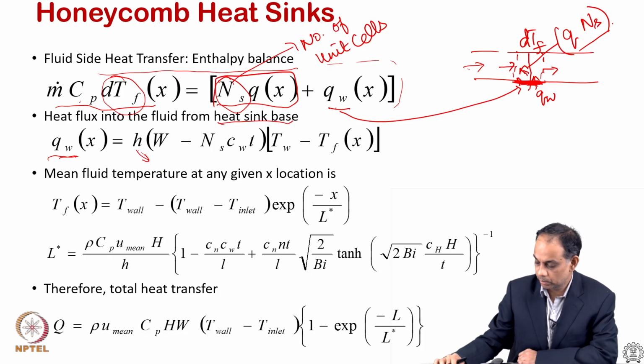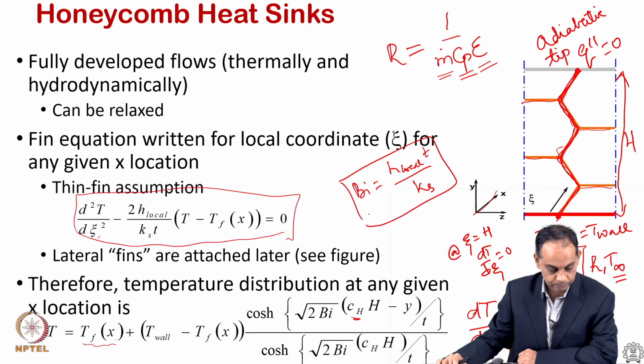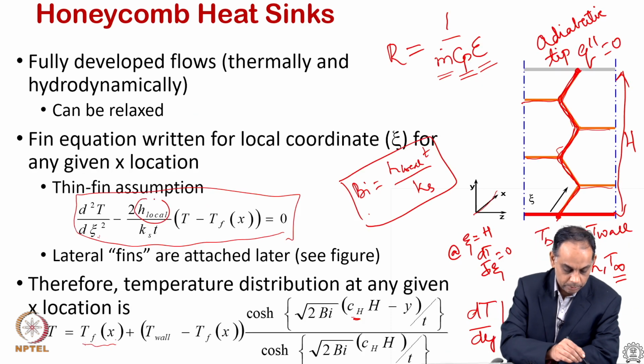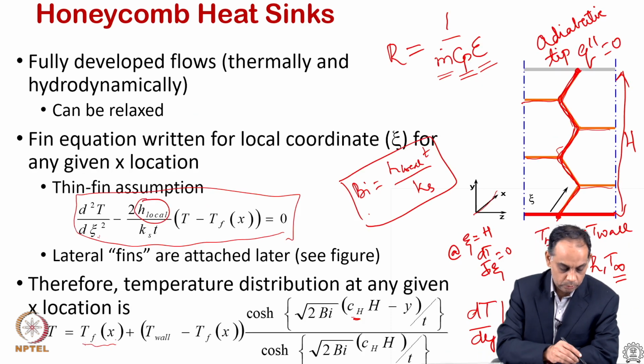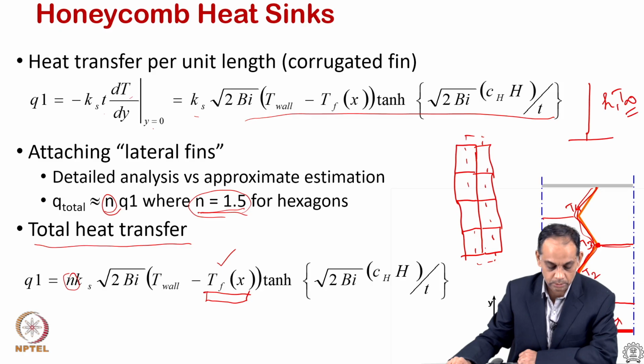So when we talk about the previous case, this local heat transfer, if it is a hexagonal duct, we use the fully developed flow expression for a hexagonal duct configuration. If it is a square, we use this relationship for the square Nusselt number for fully developed flow. If it is a triangle, we take the fully developed flow expression for triangular cross sectional ducts.